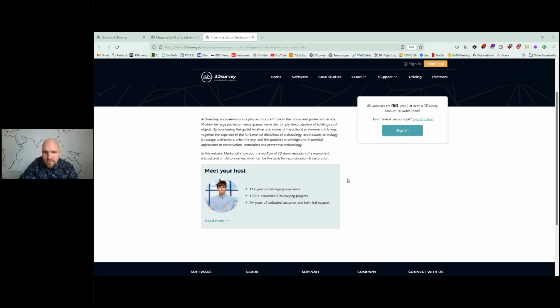Okay, back to questions. Mr. Kinkle is asking how many GCPs do you need for a project? So if you're using GCPs, I recommend at least 8 GCPs for a project. That should be plenty so that we have more measurements than we need. So 3 measurements would be minimum, 4, 5, 6 would be in between, 8 would be plenty so that we have more data than needed, so that even if we make some kind of error, we can eliminate that error.